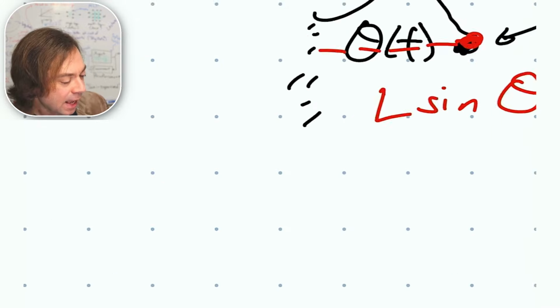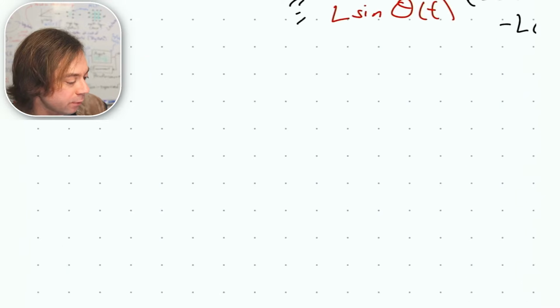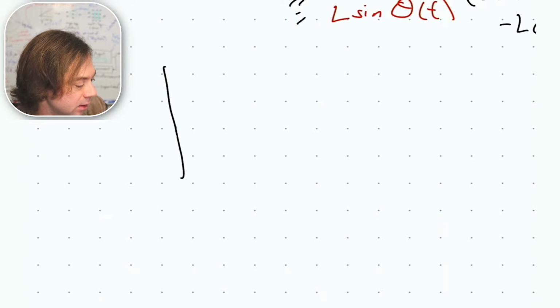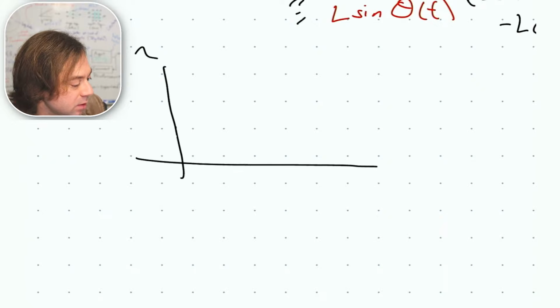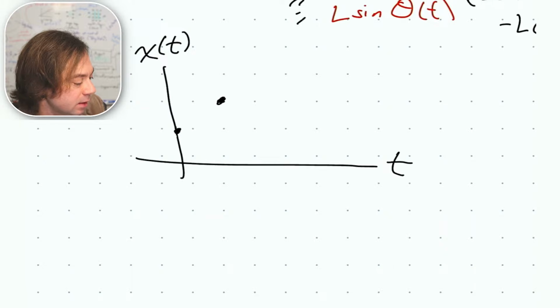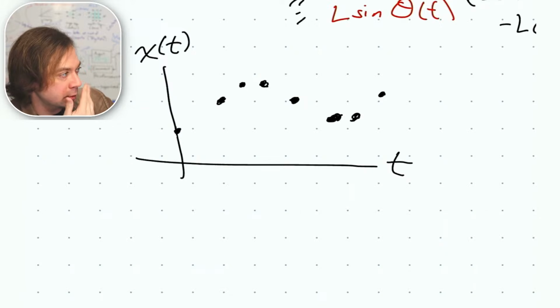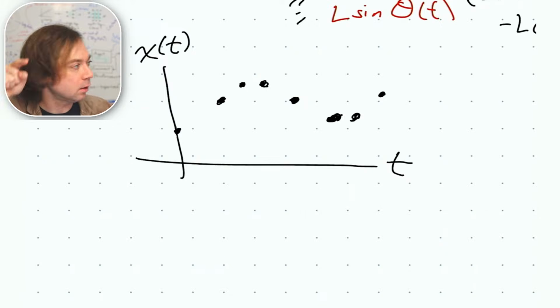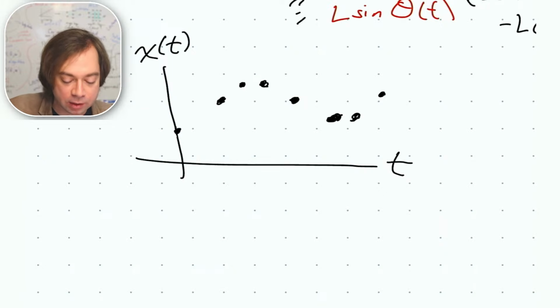What's happening with ODE45 is it is giving us a simulation of some state x of t over time, and it is giving us different time points for our simulation that might look like this. Let's plot them really quickly, not in the code, just in the command window.